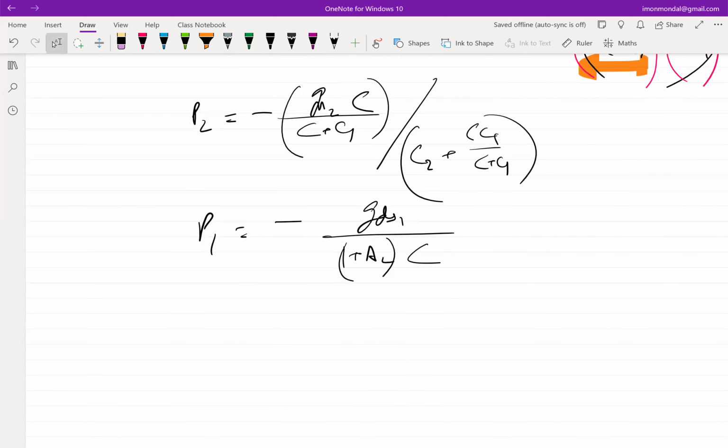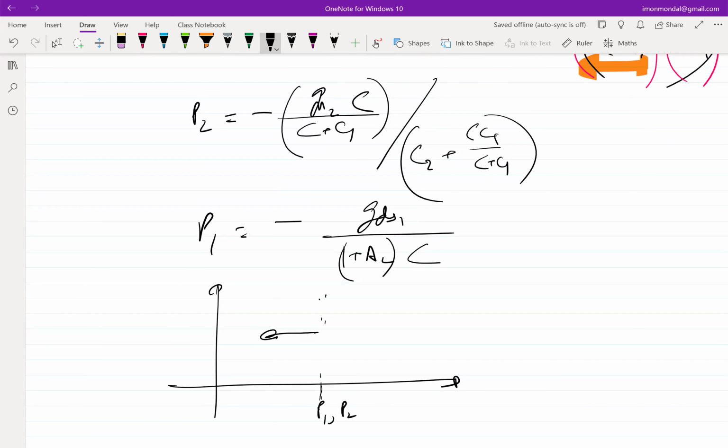So now you see that in our case, where P1 and P2 were initially uncompensated and located at the same place, after you compensated, P1 moved to the left because of this denominator getting magnified, and P2 moved to the right because the numerator got amplified, right? So P1 moves this side, P2 goes that side, which means I'm not only using a smaller value of capacitance, I'm able to get even pole splitting by pushing the poles in different directions.